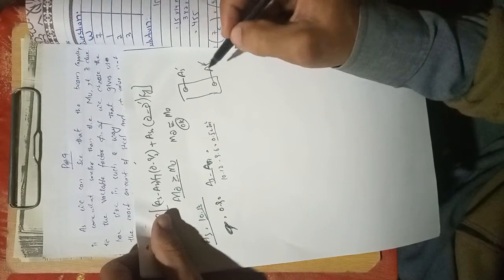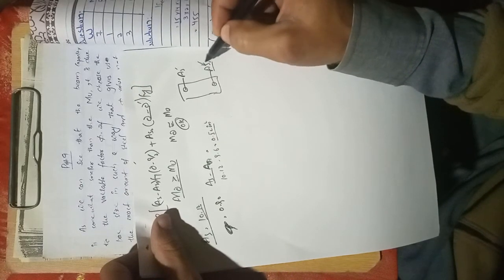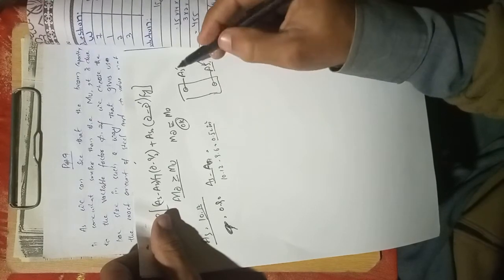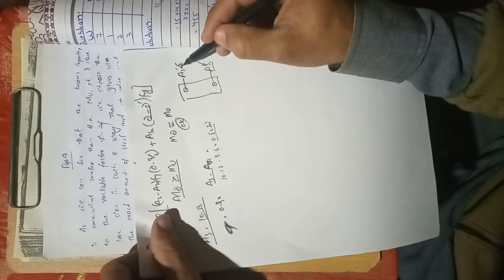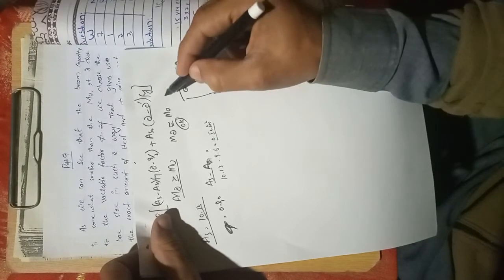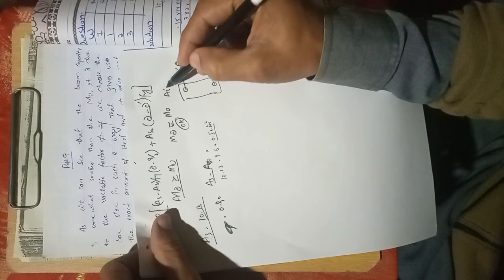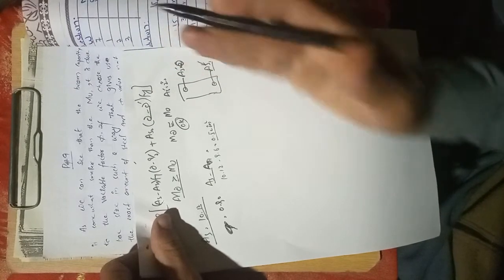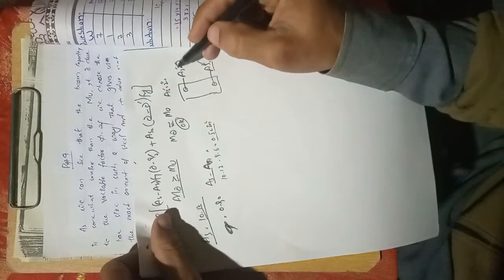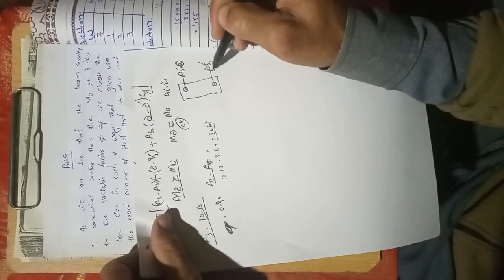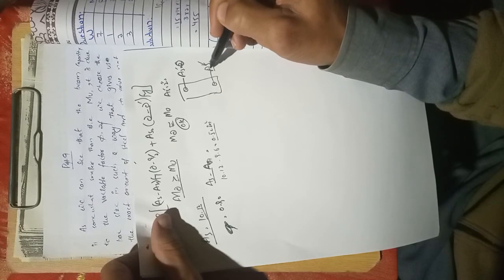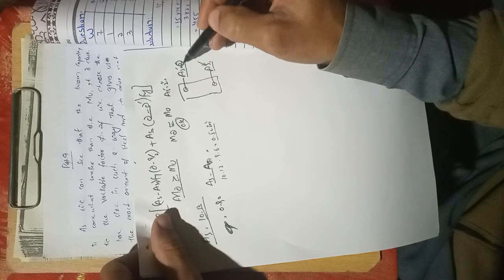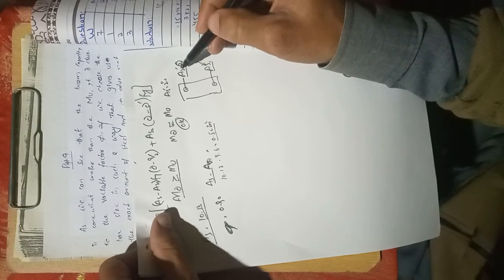This is the question. As we already increased the amount of steel from 9.6 to 10.12, and here we are using a close value, because the theoretical As prime is 2 square inches and the actual value is also 2 square inches. So that's why we will increase the As prime value, not disturbing the value of As, right? The next question is how much we will increase the value of As prime.